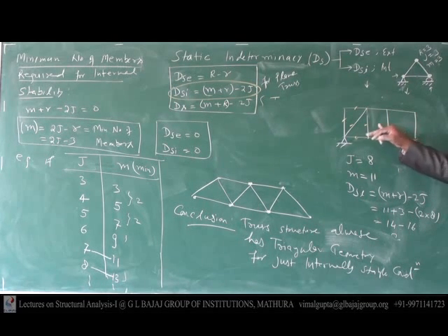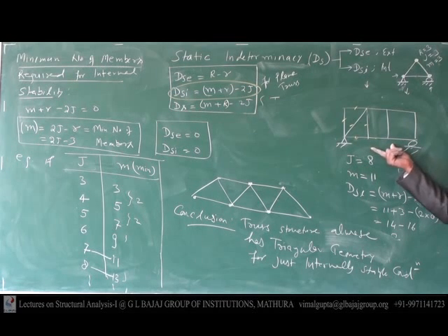Okay, so by single observation, you can tell whether that truss is stable or not by simply seeing. By simply seeing, you can tell that structure is not stable. Okay, why? It does not have any triangular geometry. Externally okay, two here, one here, externally okay.